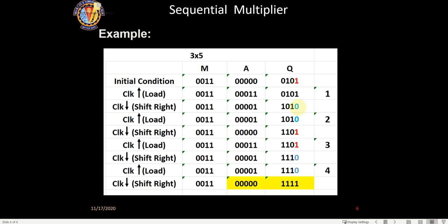Can somebody say yes or no so that I know? So basically the LSB of A got shifted to the MSB of Q, and everything shifted. Correct. From here we have pumped in 1 0 and we have thrown away the last bit here. Now it is a 0 out here.